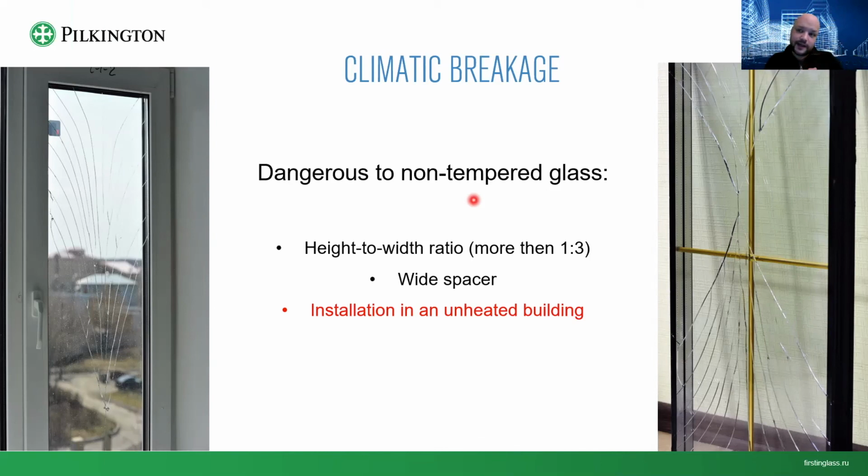But if one side of the glass is very small and the other is very big, then the ability of the glass to bend, thereby compensating the deficit or excess of the pressure, is quite limited. And where the glass cannot bend, it starts to gain stress, and stress causes the glass to break.